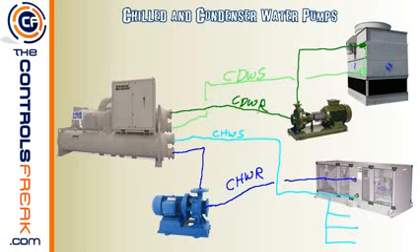The reason why is because the cooling tower is what's actually affecting that condenser water, and it's the one supplying the nice cold condenser water. So that's why we call that the condenser water supply, because the cooling tower, which is the condenser side of the loop here, is supplying condenser water to the chiller so it can use that to transfer heat. And therefore the hot water coming out of the chiller would be the condenser water returning to the cooling tower for the cooling tower to cool it back down. Hopefully that makes a little bit of sense.